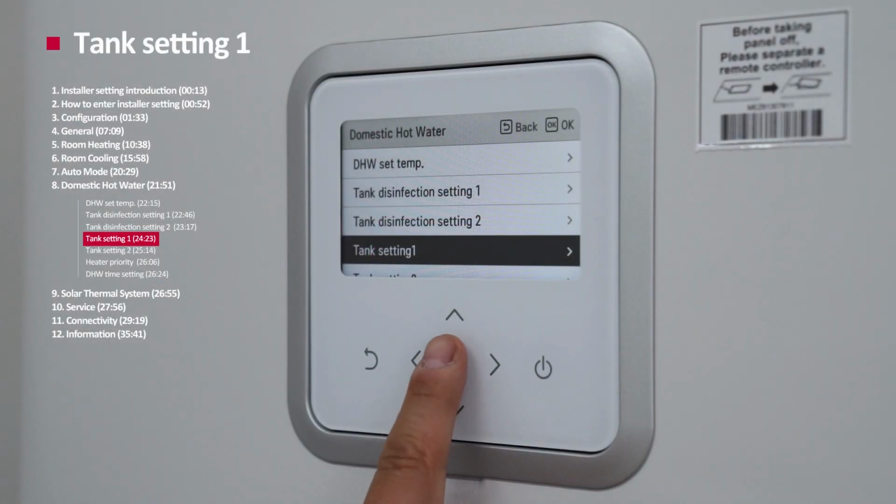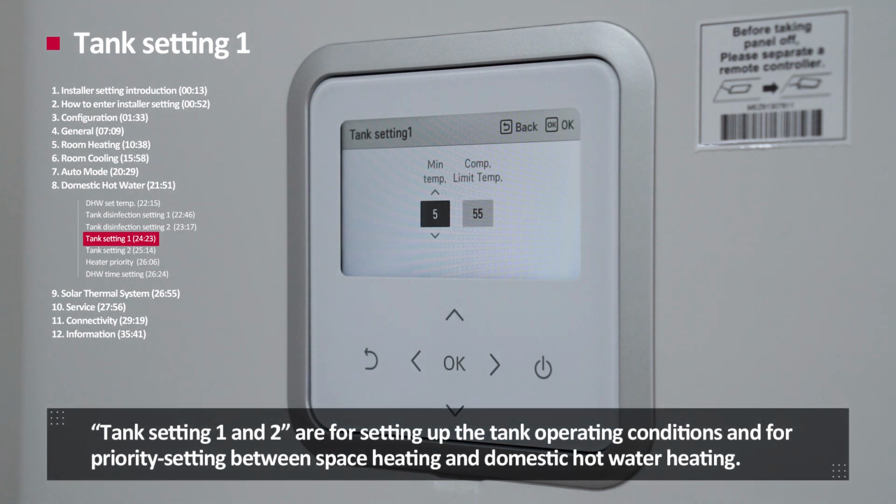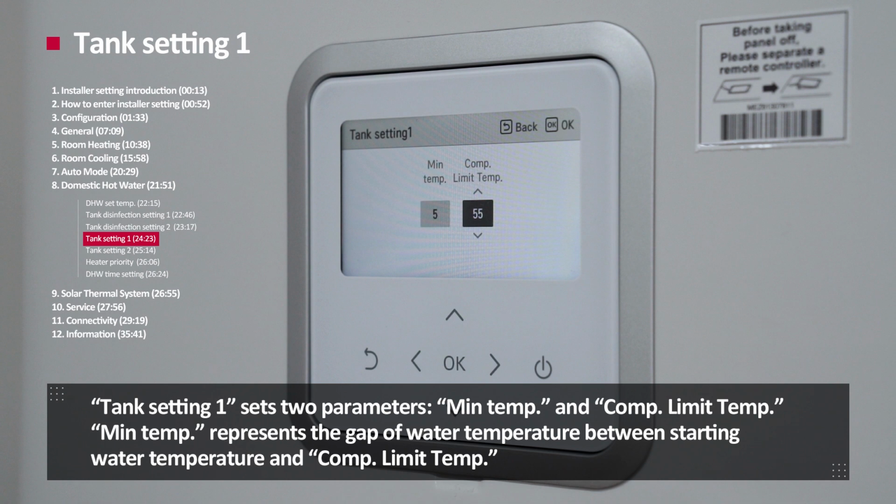Tank setting 1. Tank setting 1 and 2 are for setting up the tank operation condition and for priority setting between space heating and domestic hot water heating. Tank setting 1 sets 2 parameters: minimum temperature and comp limit temperature.